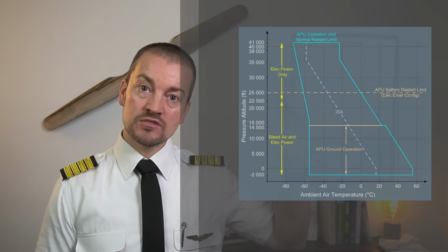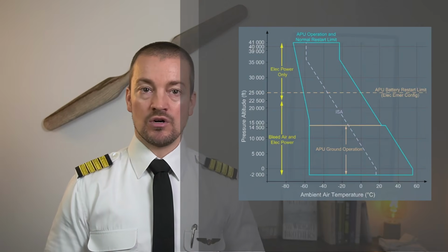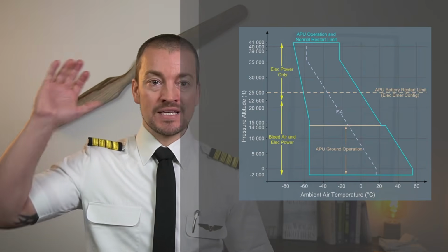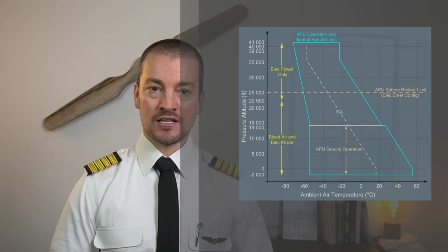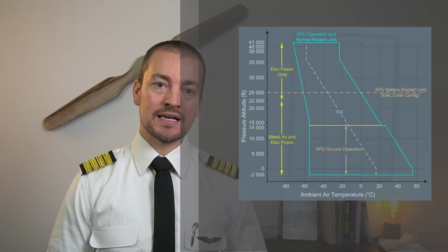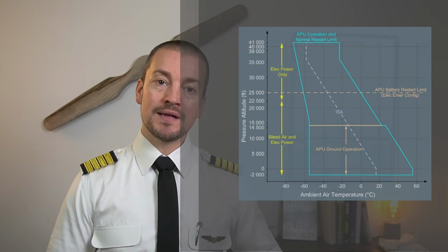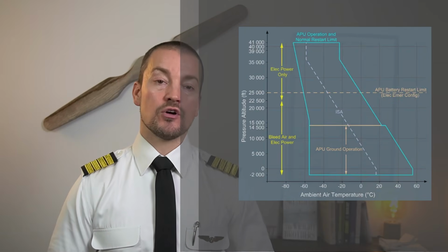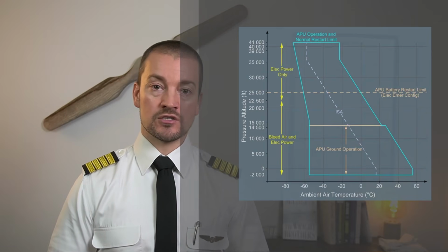And above 22,500 feet, the APU is only capable of providing electrical output. This was a limitation that was placed because of the lack of density pressure at higher altitude. The APU is simply not capable of drawing in the air to compress to also bring out bleed air while running the load compressor and the shaft for use on the other components such as the electrical generator.